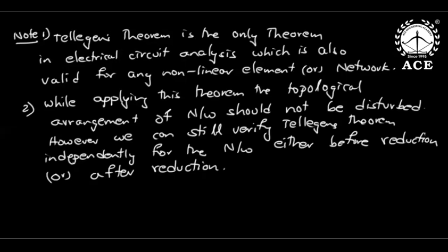That is true. And while applying this theorem, don't do reduction. Don't compare energies and powers from the previous network to the next network. Some students make such mistakes. Given a problem, they will change it and argue, sir, I'm not getting the answer. No. That is why, while applying this theorem, the topological arrangement should not be disturbed. If you disturb the network, then the effective resistance will change and currents and powers will also change. So you should not compare the given network to another network.